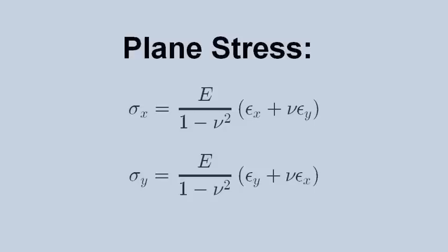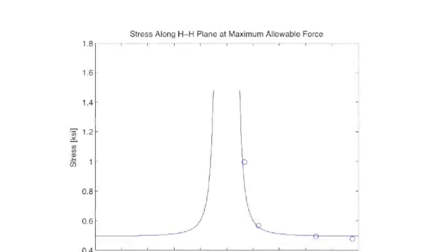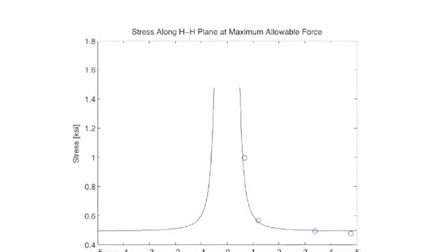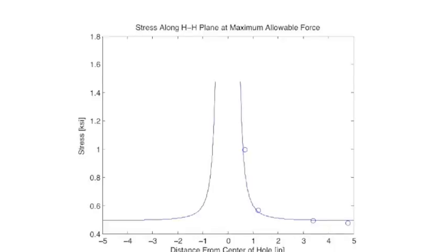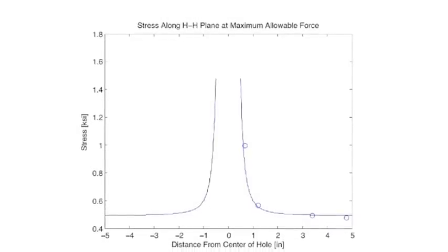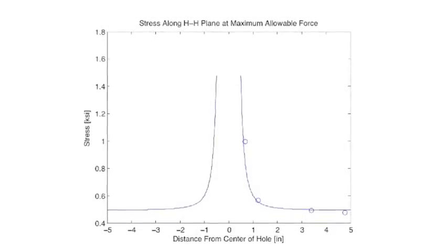Using the plane stress equation, four distinct sets of data were produced. The maximum value of each stress was taken, meaning the stress at the maximum allowable load was determined. These 4 points were plotted against their distance from the center of the hole.